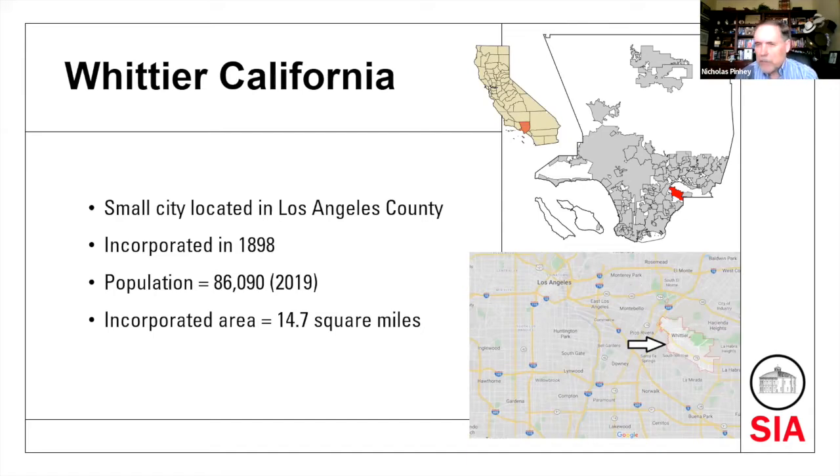This was a typical development pattern that you find in several of the small inland cities in Southern California in the late 19th and early to mid 20th centuries, where they did not have the opportunity to discharge to the ocean. The pattern was they would purchase several acres of rural land a few miles outside of the city that would be suitable for developing a sewage disposal site, preferably with the right topographic features to allow the sewage to flow by gravity. In most cases, the site would be developed into a sewer farm where the sewage, with very minimal treatment, could be used for irrigating crops such as alfalfa or walnut orchards.